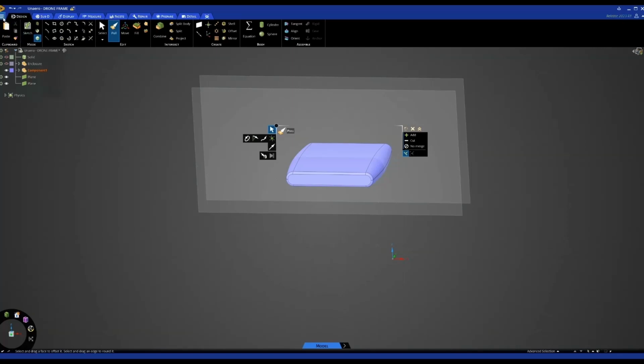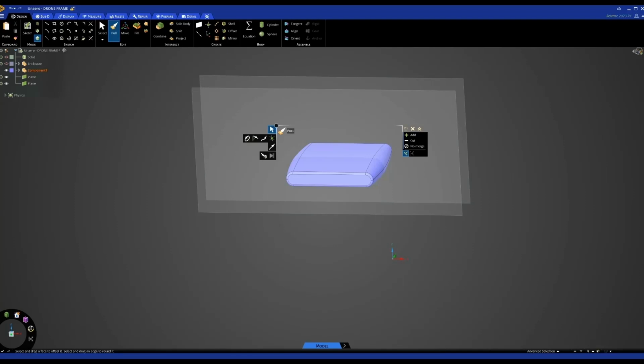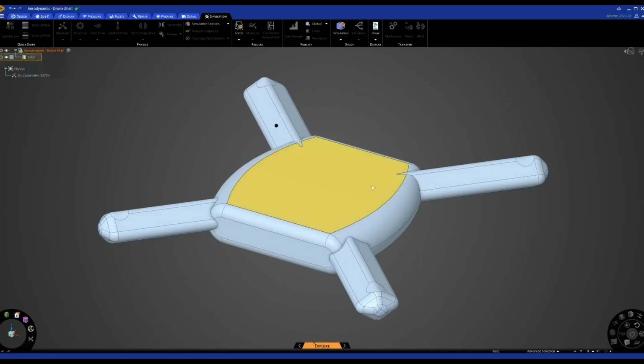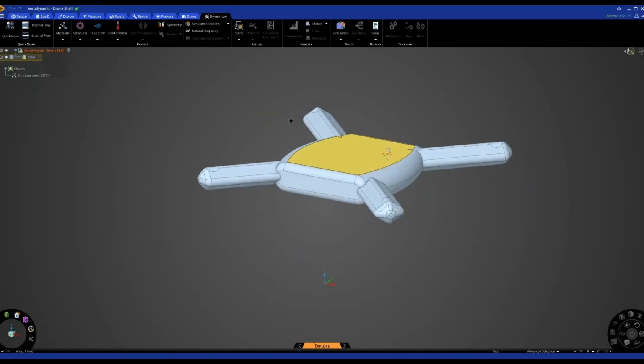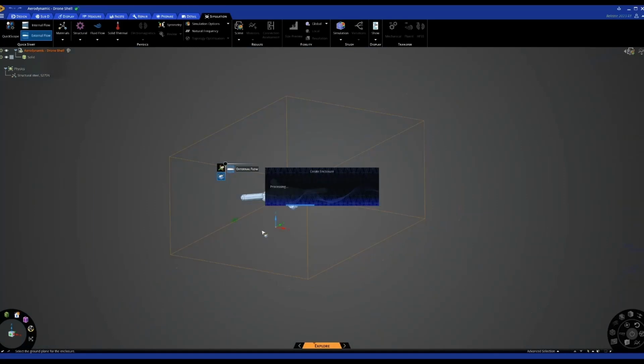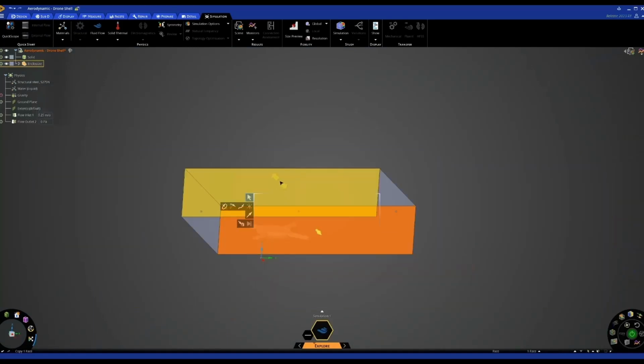But what I'll do is I'll open up the finished model, which is our more aerodynamic shape, and let's just run a quick simulation on that, just to show the results on a more potentially aerodynamic shape of our drone skeleton. So exactly the same setup. We go into external flow, choose our inlet, choose our ground plane. As I did previously, you can modify this fluid zone.